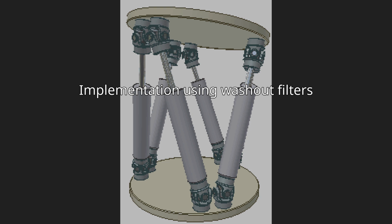Three common types of washout filters include classical, adaptive, and optimal washout filters. The classical washout filter comprises linear low-pass and high-pass filters. The signal into the filter is split into translation and rotational signals.